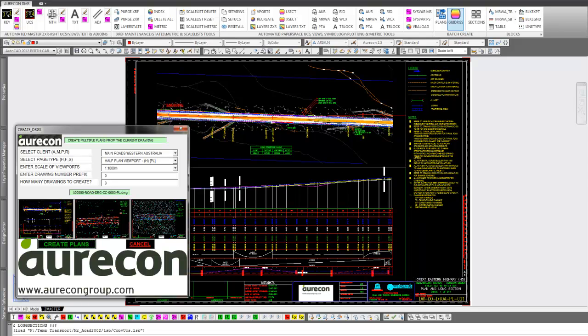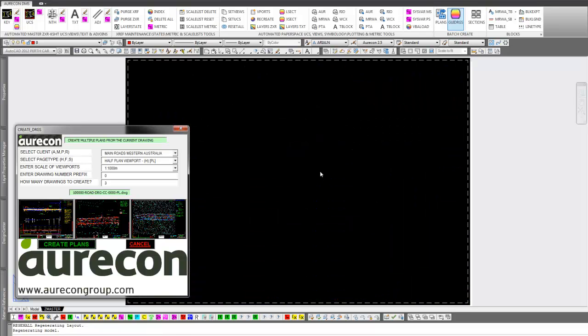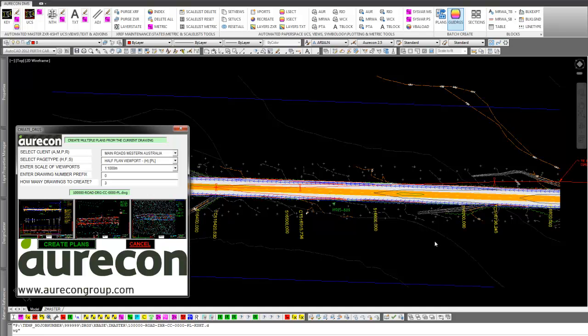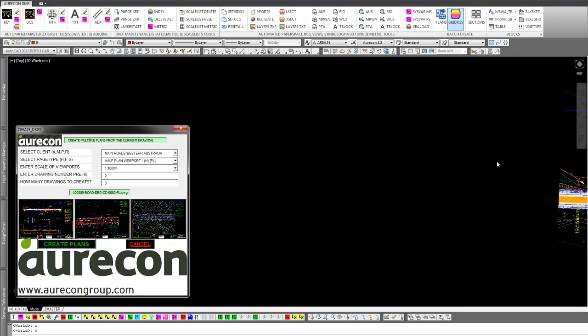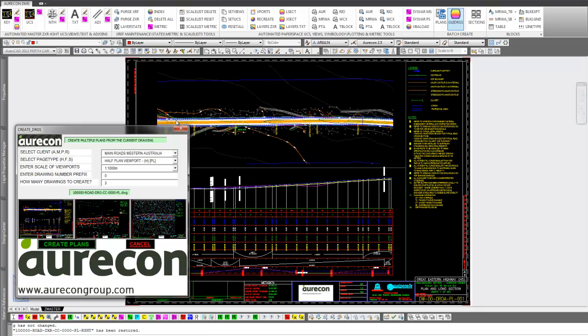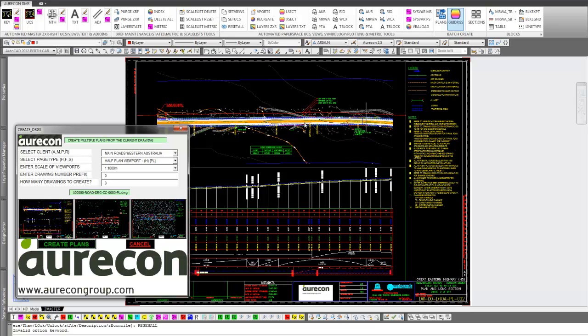It's now saved to drawing number 2 that we can see up here. Again, it's loading the VLX files that we can see down there. Again, it will pop over to model space momentarily, and again, it will need to unclip the previous viewport 1, restore the UCS and the view of the file I just imported via the VLX files, clip it to the extents or the limits required in the plan, pop into model space, unlock the viewport, restore that UCS and view, align the extents of works, mask on and off the appropriate text layers for the subject, and detach and reattach the appropriate long section, which it looks like it's done.